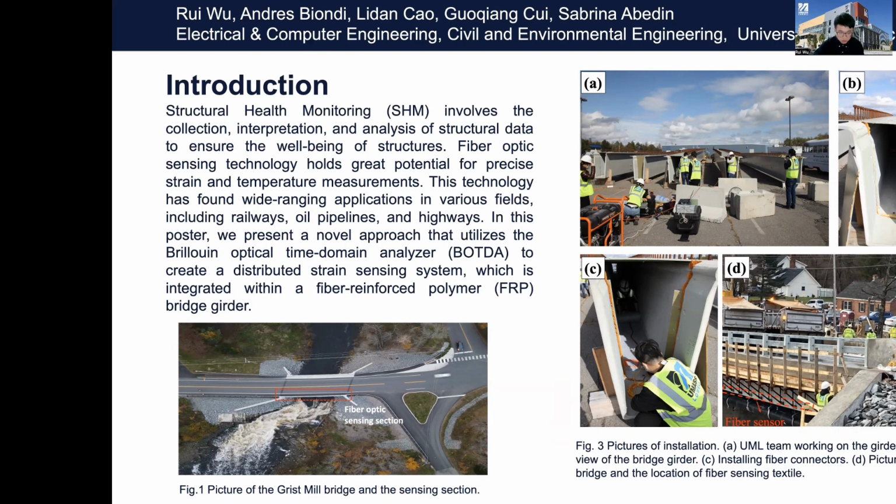In this poster, we will present an innovative approach that utilizes the Brillouin optical time domain analyzer, short as BOTDA, to establish a distributed strain sensing system, which we have integrated within a fiber-reinforced polymer bridge girder.